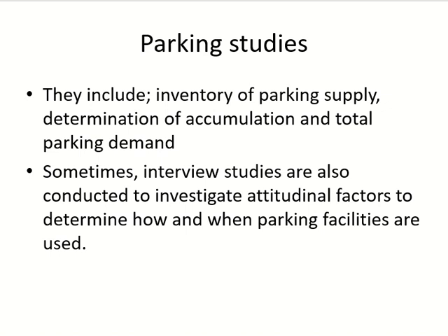Then we have parking spaces, record. Then we have accumulation. Accumulation means at a given time how many spaces are occupied. And then we have parking demand. Parking demand means in the whole day how many vehicles have used the entire area, or in a specific time period.